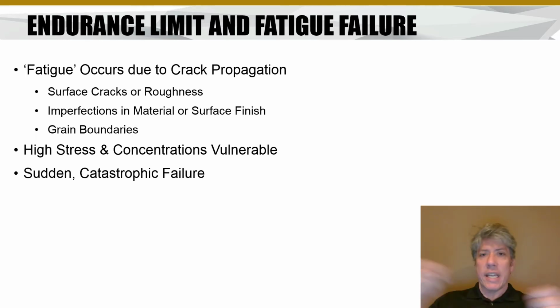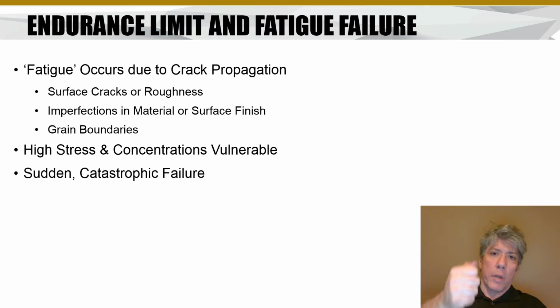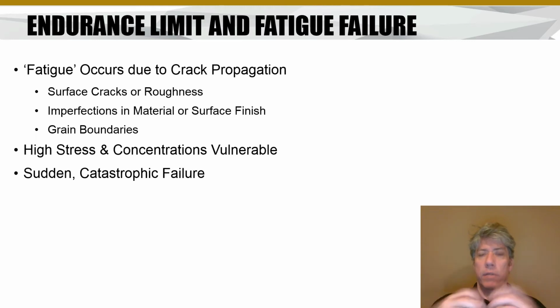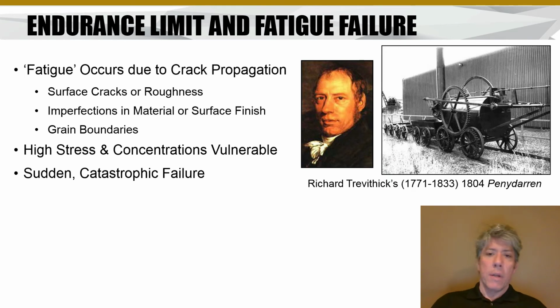You don't see any necking down like you do when you take a dog bone and you pull it apart slowly in a tensile machine. Rather, what happens is you don't notice that there's a crack growing, and all of a sudden the part fails, and it can be a catastrophe. As a matter of fact, it has been in the past.